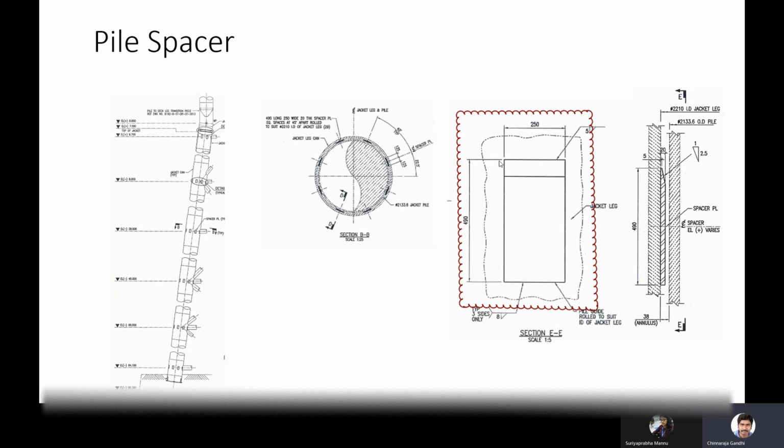In offshore, people will fight for each weld. If you are giving, for an intermediate weld, for the 10 thick plate to the deck plate to the beam, more than 5, they will question why you require a high thickness of weld for grating. When you are giving some standard things, we have to be very careful what we are giving.